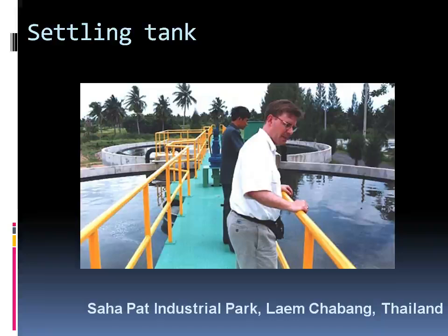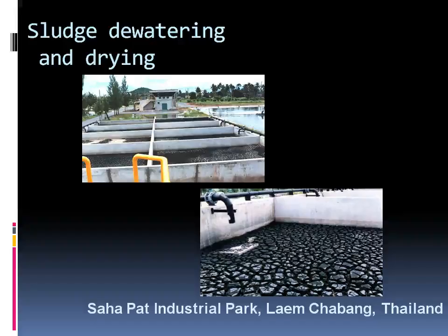Both primary and secondary treatment remove about 90% of the oxygen-demanding organic waste. However, most of the salts, nitrate, phosphate, pesticides, and radioactive materials still remain in the waste streams. As most sewage plants have only primary and secondary treatment facilities, a large amount of plant nutrient is still being added to water bodies.